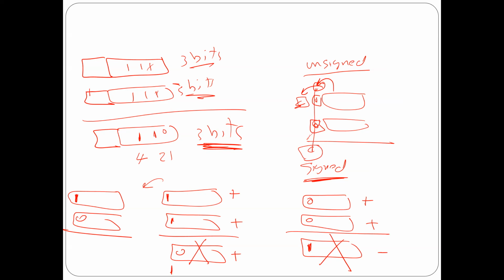Again, in case of unsigned numbers, I told you what you have to do. You have to store the number in bigger space. Always when you do extension, you are going to put 0, 0 all the time in unsigned numbers. So if I put here 0, I put here 0, and there is a carry here, you are going to add this carry plus 0, and you are going to get the carry. So as a shortcut in unsigned numbers, you can take the carry and consider it a part of the answer, and it's going to be correct.